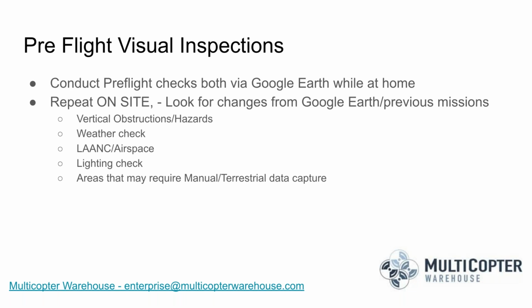And in fact, in certain conditions, those lower noise props are worse for mapping. At altitude, they don't hold a position as well, and it just feels a little sloppy as you go higher up in altitude. If you're at sea level or whatever, they're awesome. They're great. But when you start getting into the 6,000, 7,000, 8,000 feet above sea level, those low noise props don't feel the same.